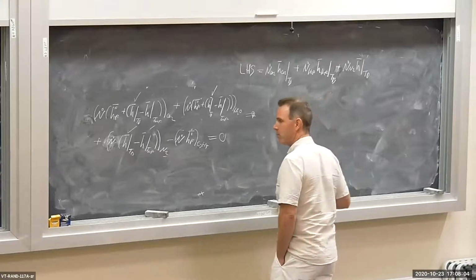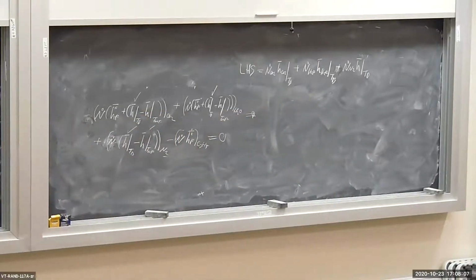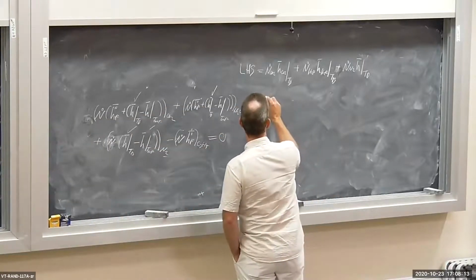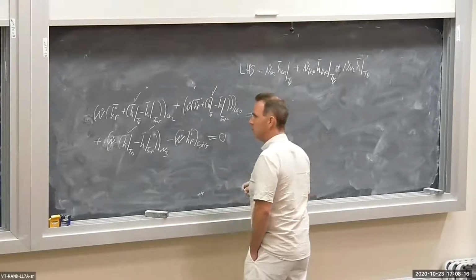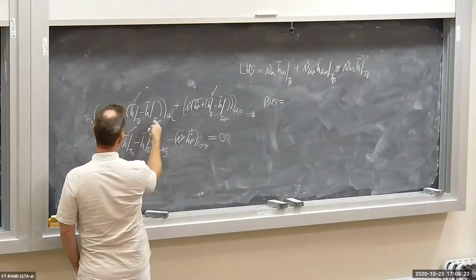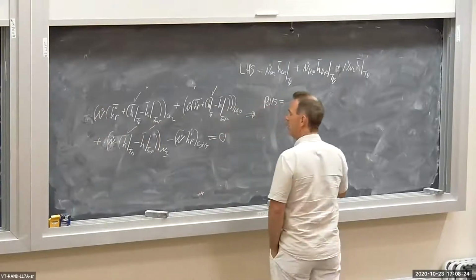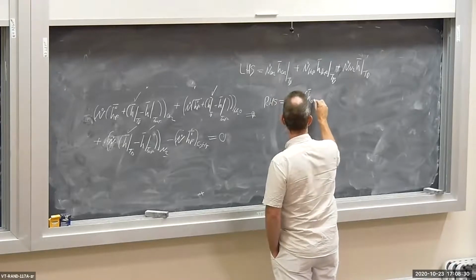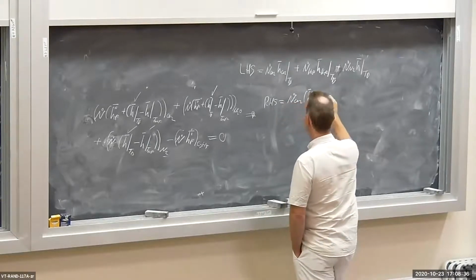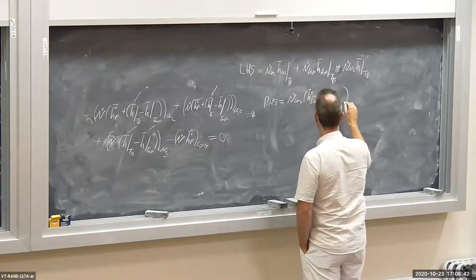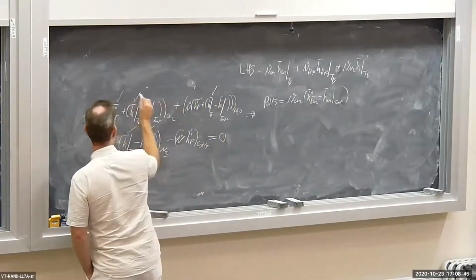Well, I'm going to take the N dot for the CO2, the H naught sub F, and the H ref term. So I get N dot CO2, H naught sub F for the CO2 minus H bar for the CO2 evaluated at T ref. So that takes care of this term and this term.